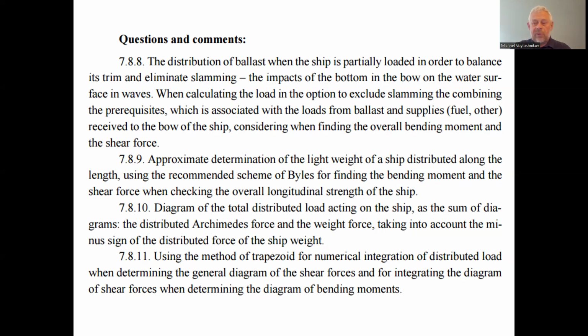And besides, we have to adopt the definite ballast and the stocks of fuel and fresh water for the ship consumption. And another peak to keep the balance of the trim at the appropriate level, to exclude the slamming, because consequently we can, in the check of the strength, not consider so much the possibility of the fatigue failure, which can be the result of the slamming, fatigue failure of the ship.